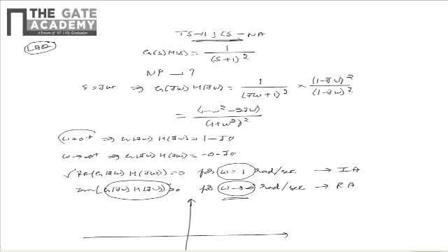From this, we can plot the Nyquist plot as ω varies from 0+ to infinity+ as shown. At ω = 0+, G(jω)H(jω) is 1 - j0. That corresponds to the point marked. And as ω tends to infinity+, the Nyquist plot value is -0 - j0. That is, it approaches the origin through the third quadrant. And also it is given that the Nyquist plot intersects with the imaginary axis for ω = 1 radian per second. From this, the Nyquist plot can be obtained as shown.